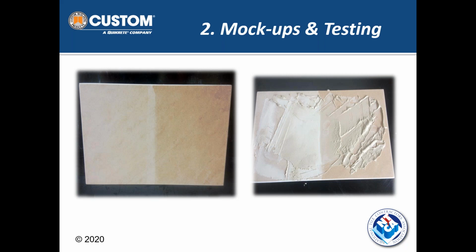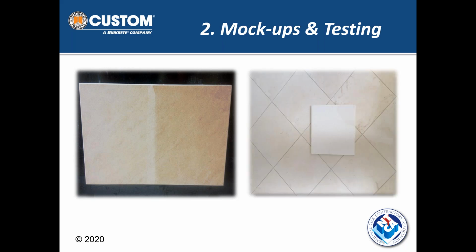Now, it's not very obvious until somebody does this and they start putting the stone down on the floor saying, that doesn't match. Why does it look darker than the material was supposed to look like? Initially, without that piece on the floor, you would look and say, well, that's a nice average looking floor. But when the owner takes a piece of stone and puts it on the floor and says, that's a lot darker than it should be, it's typically due to the fact it was never pre-sealed and you actually have a degree of staining going on in the stone.